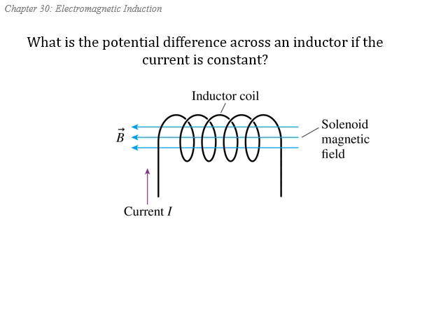Start with a simple question. What is the potential difference across an inductor if the current is constant? I'm going to invite you to pause and answer for yourself first before you unpause. Okay, now you've had time to think about it. So let's remember the first thing we said about our inductor. An ideal inductor has a resistance of 0. So according to Ohm's law, the potential due to the resistance of the device would be V equals IR equals 0.